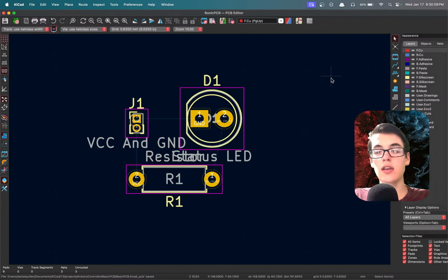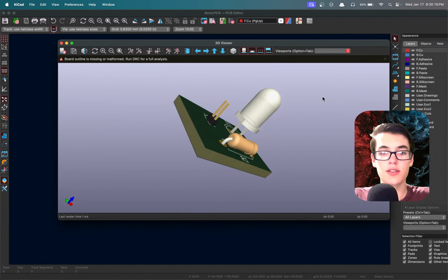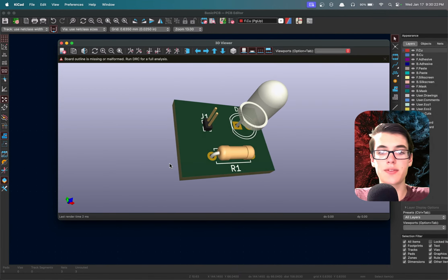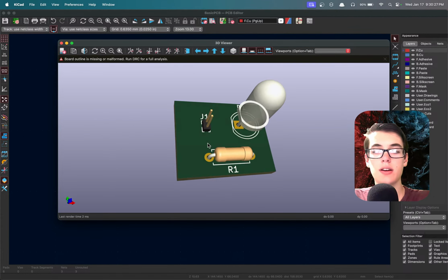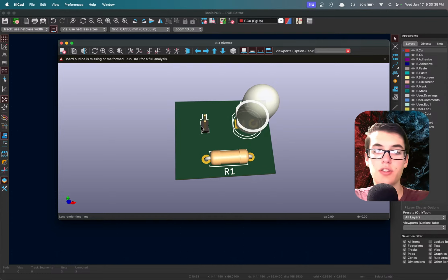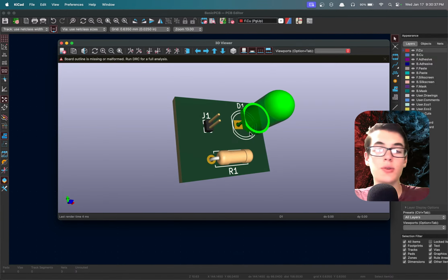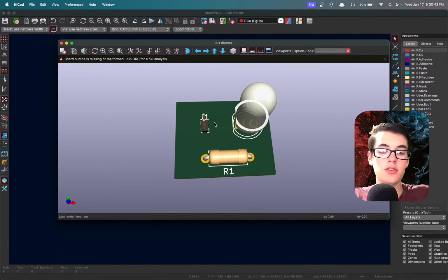And then on top of that mask layer is a layer that is printed words. So we have copper, that's this gold stuff, covered in most places by a mask, which in this case is green, but uncovered in some places. And then we have the silk screen, which is these little lines on here, which are all white. And this can be words, symbols. If you want to put your company logo on there, you would do that with a silk screen. After you print out the PCB, you draw those things on there, so it's easier for the assemblers.